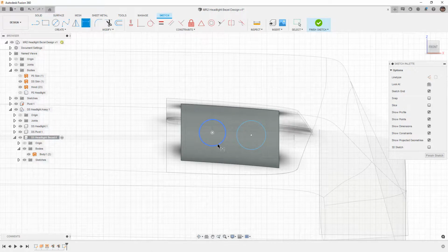In this case, I'm going to go ahead and use my dimension tool. I'm going to make them both 50 millimeters. Seems like a good number. If we want to make these 2 dimensions exactly the same, we can link them by clicking on the first one. That way, if I change this one to 55 or whatever, then we can do that. You can also use the equal constraint as well instead of a second dimension. This can be helpful, especially if we want to control a lot of different things with a dimension. For example, if I wanted this one to be 5 millimeters smaller, I could just say -5. And if this one goes to 75, that one's going to be 70 and so on. So it can be a good way that you can connect these two.